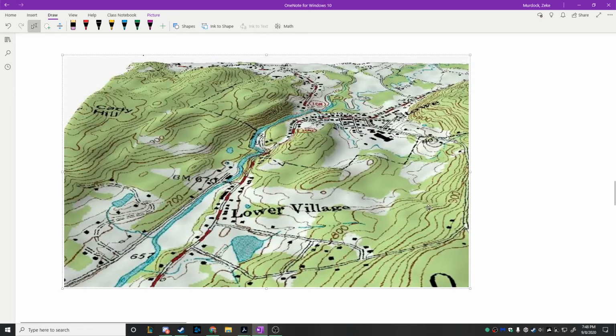The closer together the lines are, the steeper the slope is, right? The farther apart they are, the more gradual it is. And in regions like this, this is a big flat area, right? Big flat area here, big flat area here. Obviously some flat areas next to the river, but then there's a steep slope next to the river here. And this region right here is really steep, right? That's a very sheer face because the lines are super close together, okay?